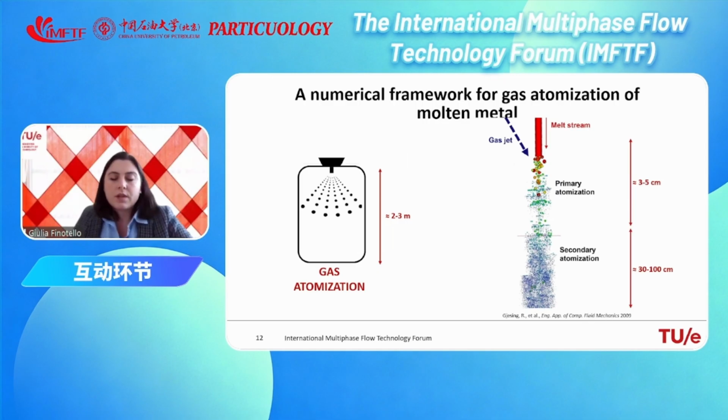Yeah, so that's why I also mentioned that choosing a plane might not be the best way, because you are really just choosing a sharp division between the primary and secondary atomization. Of course, this is not what happens in reality. There is some transition or overlap of both mechanisms. What you see is a core of the melt, which is broken into larger droplets and larger ligaments.